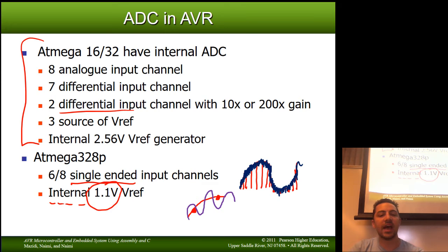All right, so this is the actual signal. It's following along the path of the sine wave, but there's this low magnitude, high frequency noise. So now look at where those samples are actually taken. This sample is taken up here, and this sample is taken down here. So instead of reconstructing this nice arc here, it looks like it's actually decreasing, which is bad. We definitely have a sine wave that's increasing at this point, but because of the high frequency noise, it looks like it's decreasing. So high frequency noise, bad. We'd like to get rid of it.